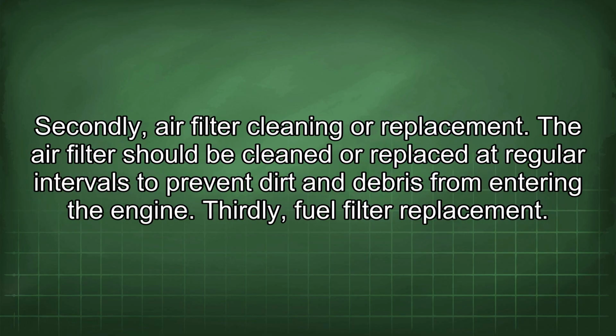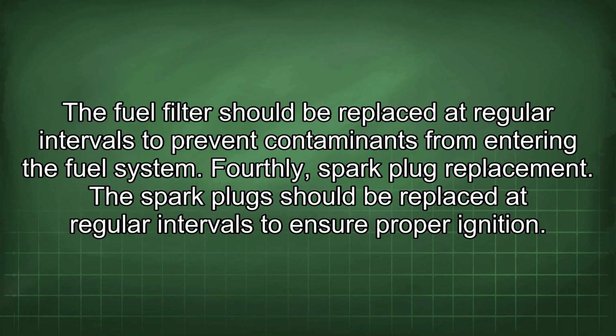Secondly, air filter cleaning or replacement. The air filter should be cleaned or replaced at regular intervals to prevent dirt and debris from entering the engine. Thirdly, fuel filter replacement. The fuel filter should be replaced at regular intervals to prevent contaminants from entering the fuel system. Fourthly, spark plug replacement. The spark plug should be replaced at regular intervals to ensure proper ignition.